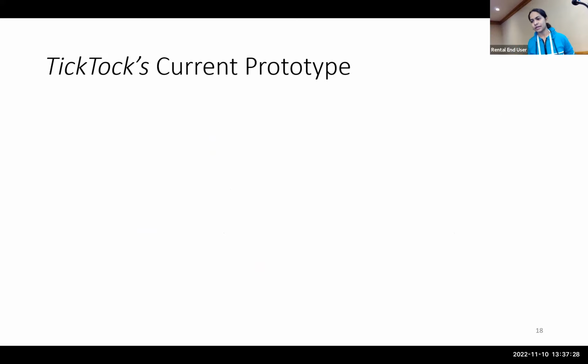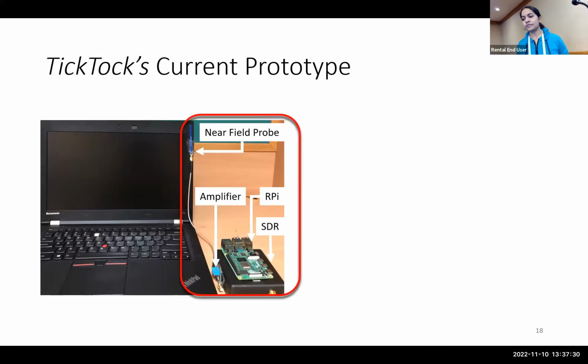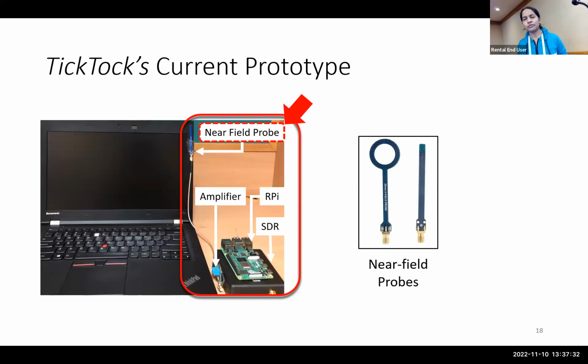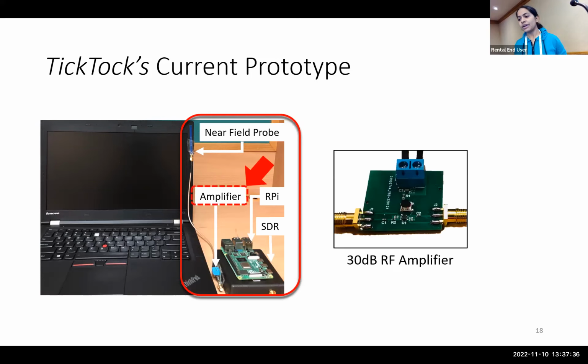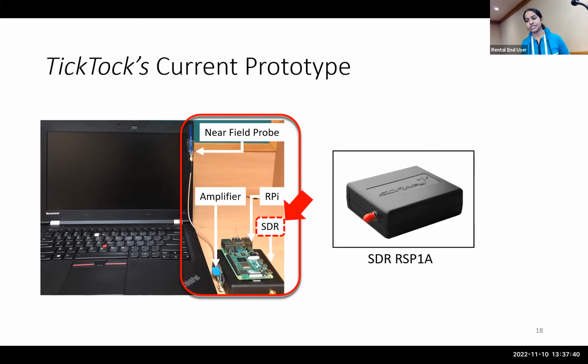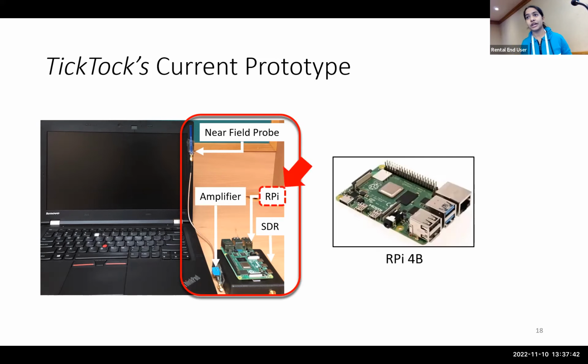So now that we've seen the high-level design of TickTock, I would like to switch gears to talk about our current prototype. So our prototype consists of a near-field probe, which is essentially sitting in contact with the laptop to pick up the EM leakage. And we have a 30 dB RF amplifier and a software-defined radio, which is digitizing the signals, and an RPi, which is running TickTock's core logic.